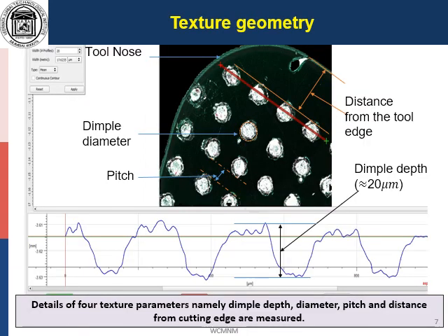As I said before, microtextures were imparted on the rake surface of coated and non-coated tungsten carbide cutting tools by using Ytterbium laser. Micro-cavities of circular shape were machined on the tool surface. Circular shape micro-cavities were selected as they are axisymmetric and not impacted by the flow direction of the chip, unlike triangular and rectangular micro-cavities.